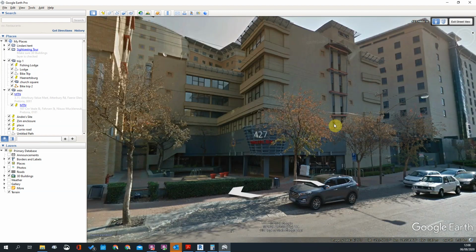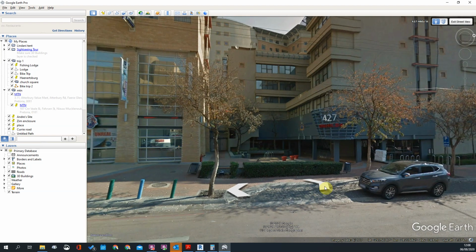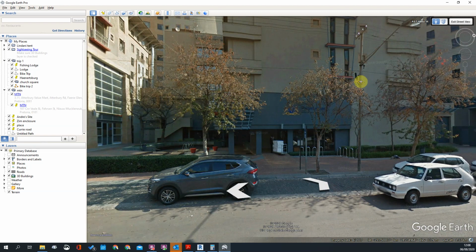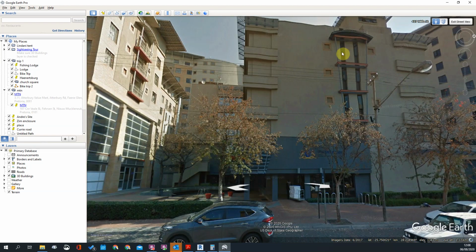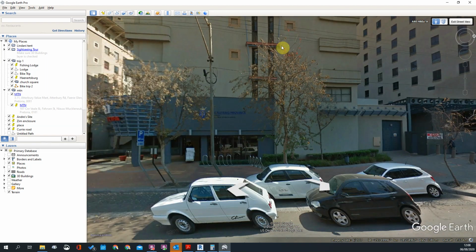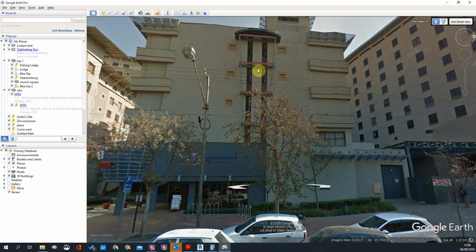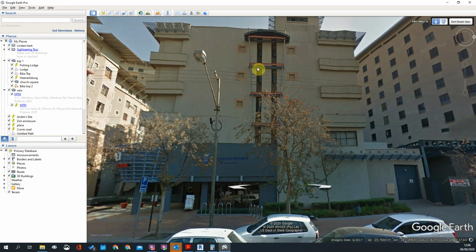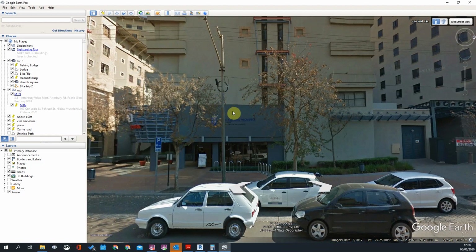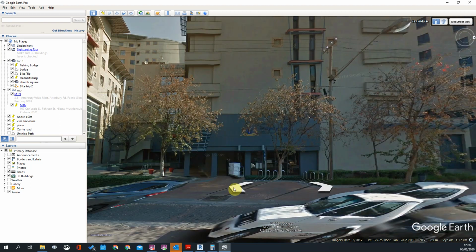And also for this wall going up and down here, I've got a feeling this is a curtain wall system that sits in there, and it's got solid and it's got panels in it that open and close. So you can see there's something happening here. I've got a feeling that it's like a curtain wall system that goes up and down, and that's how we'll show it. And you can see the slab edges come through at certain areas. So you probably find that the slab comes through and it's like a curtain wall system that just sits in there with the solid panel, and that's how it's easier to build.